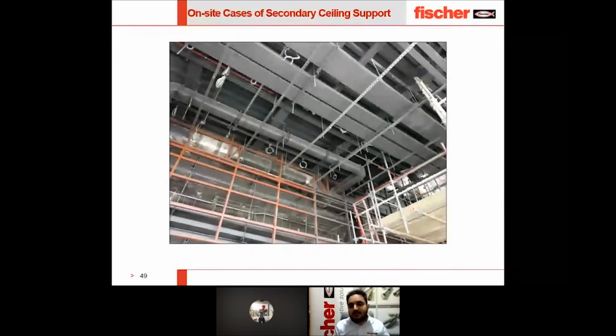In this case it's different. For Mustafa, what was the deflection limit considered? In this case it was L/300. This is based on the false ceiling manufacturer's recommendation. We follow the recommendation of the false ceiling manufacturer, because they test their system based on that limitation.